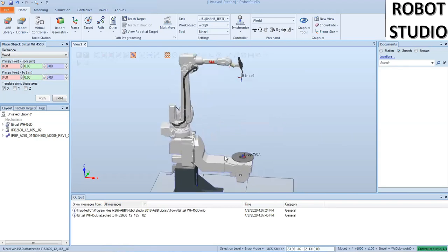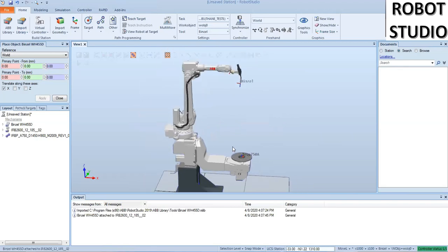Now, all that work has been done by ABB so that it can happen that way. We'll go through the manual steps on how to define those in another video. So now we go to the positioner, and the one thing we need to do to the positioner is create a user frame and a work object for this system. Most importantly, the user frame at this moment.